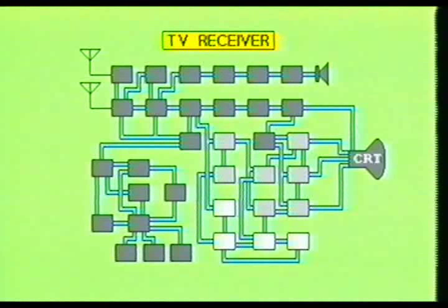The phase of the chrominance signal is very critical for proper color reproduction. Any deviation from the phase of the subcarrier at the TV broadcast transmitter will result in a change of color at the television receiver. Since even a slight variation of the carrier from the reference phase will cause a change in color, it becomes necessary to use signals which synchronize the reference signal to the carrier signal.